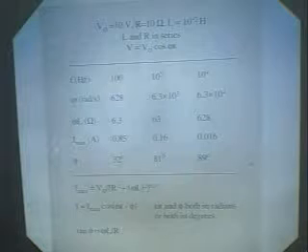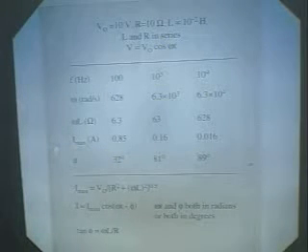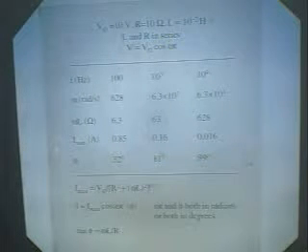You see an L in series with an R. The L is 10 millihenry, and the R is 10 ohms. And let V0 be 10 volts. And here you see three frequencies, 100 hertz, 1000, and 10,000 hertz. And here you see the values for omega. You have to multiply hertz with 2 pi. And look now at omega L.